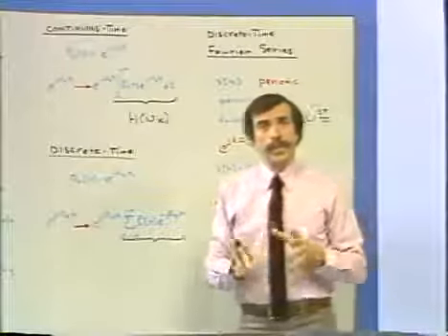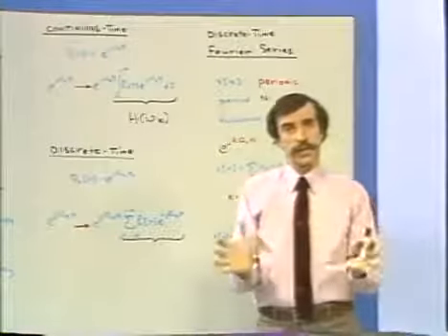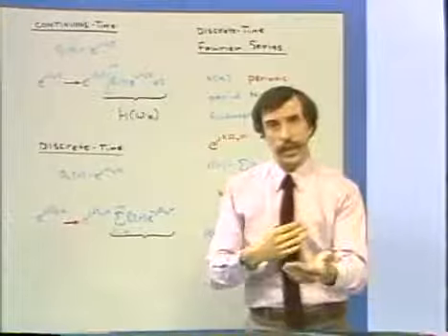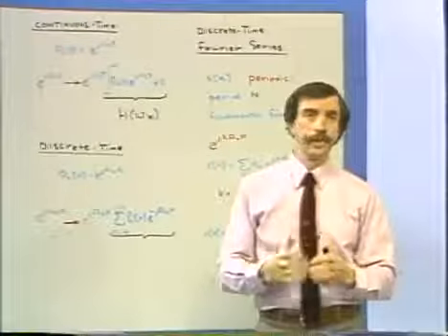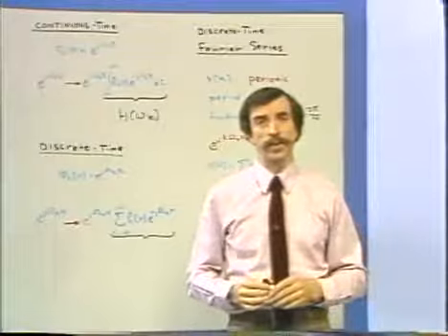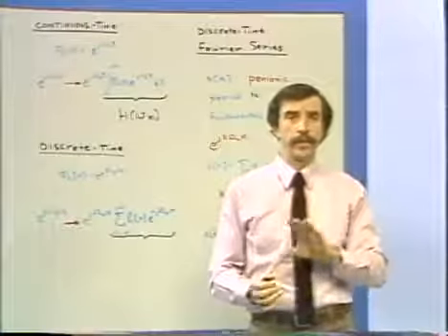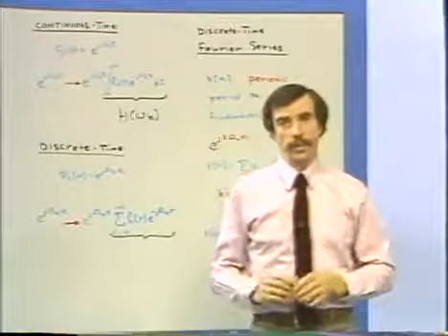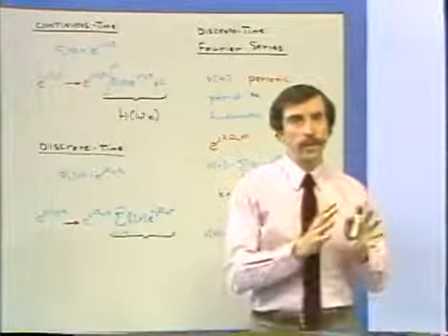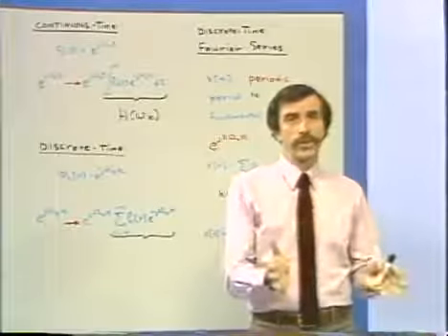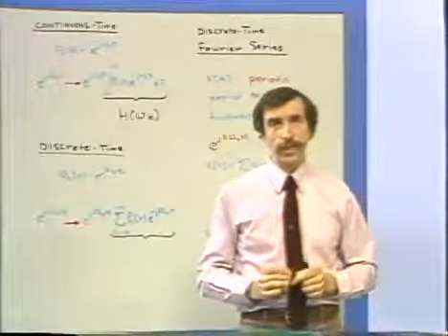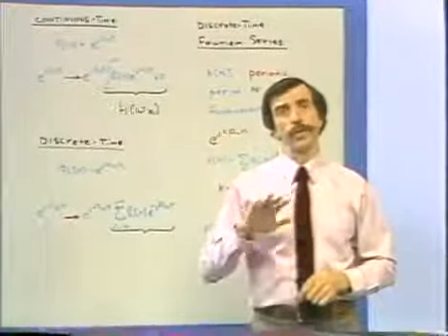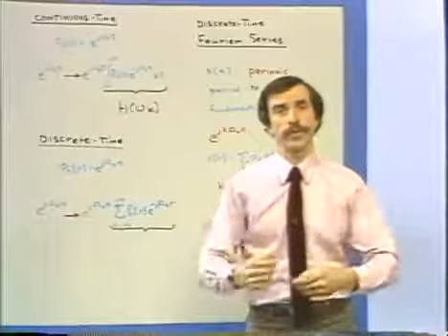And the notion of decomposing a signal as a linear combination of these complex exponentials is what first the Fourier series representation and then later the Fourier transform representation corresponded to. And finally, to remind you of one additional point, because of the eigenfunction property, once we've decomposed the input as a linear combination of complex exponentials, the response to that linear combination is straightforward to compute once we know the frequency response.